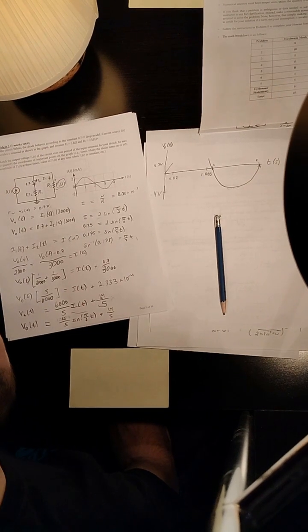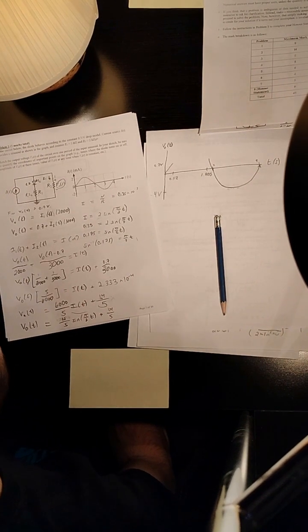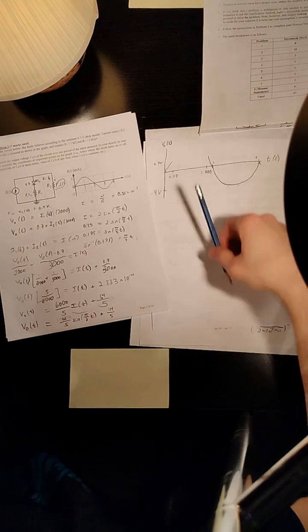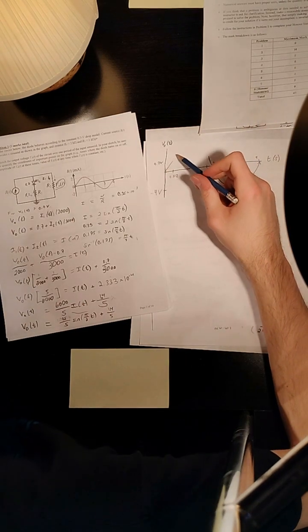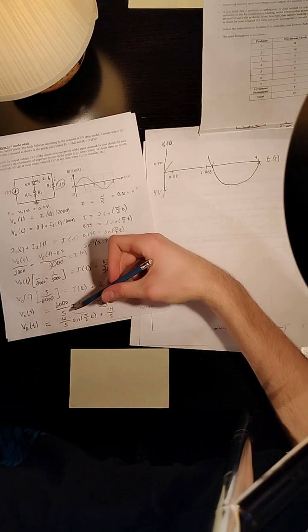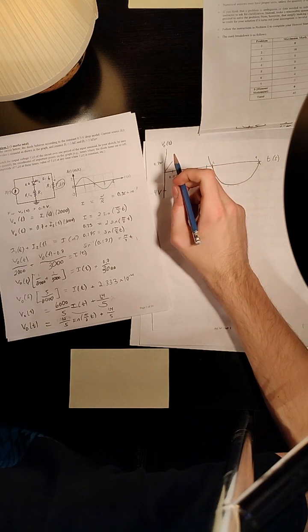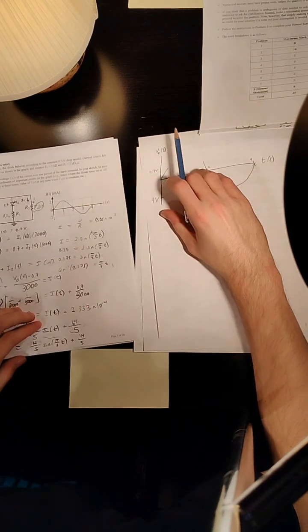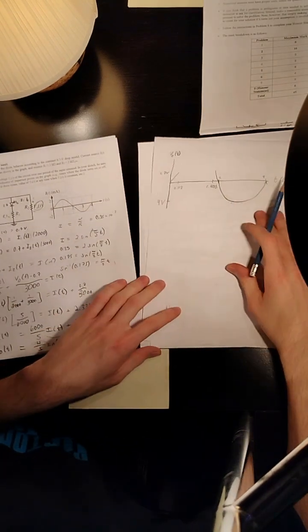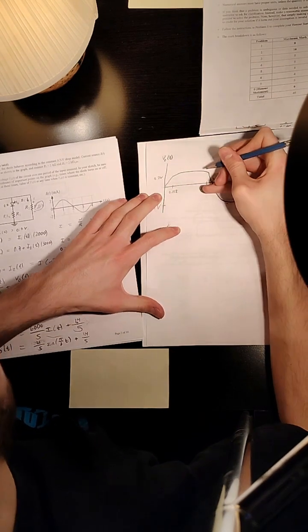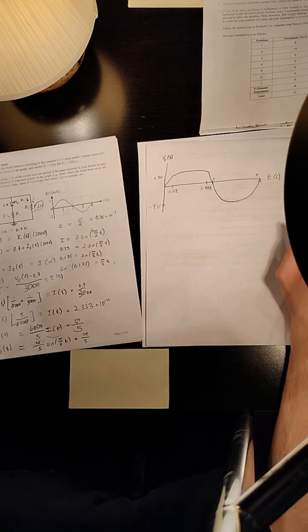So what does this say? This says that your maximum VO of t is less than what this sinusoid had suggested, right? The maximum here would have been 4, but with this new sinusoid, your maximum is only 2.4. Which makes sense, because now the current has 2 different ways to go. So the voltage required to send that current is a little bit less. So your thing is going to look a little bit more clamped off like that. We've seen that in the labs.